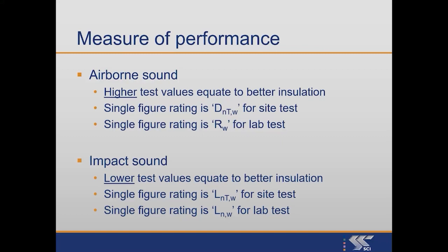The nT is that it's been adjusted for the reverberation time, standardized reverberation times. We don't have that with the lab test because actually the lab facility will have been adjusted, with baffles and acoustic hangings within the spaces, so that they have got a reverberation time of that half a second for their laboratory. And then impact sound,